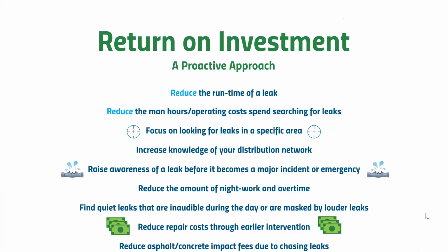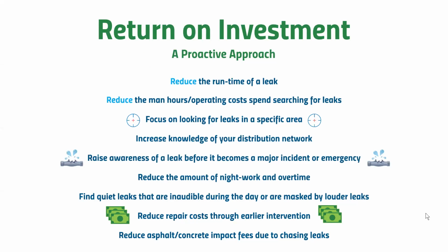Knowing this, the return on investment is quite visible for a leak detection program. An effective leak detection program with the right equipment, efficiently run, is going to provide numerous paybacks, not only in the elimination of the loss of your water, but reduction of man hours repairing pipe, the reduction of chemical costs for your treatment of your water, the reduction of your electrical pump costs for pumping of the water, and the reduction of your mainline breaks. Finding the leaks when they're small pinholes will stop that leak from becoming a main break 2, 3, 4 months down the road.